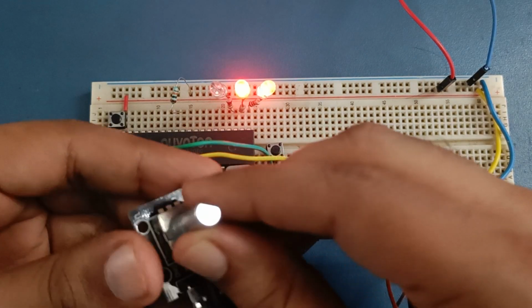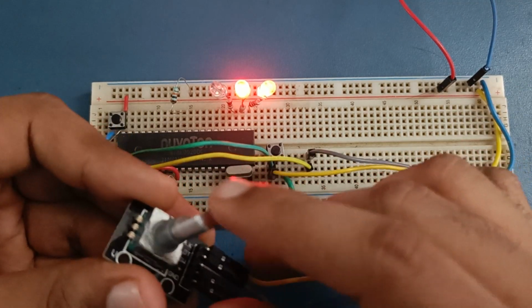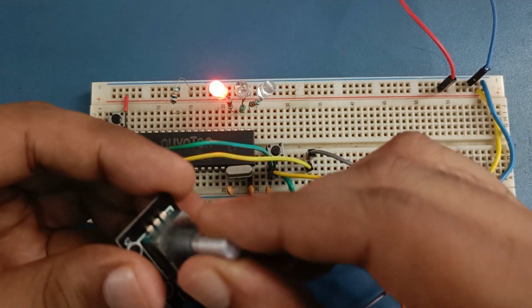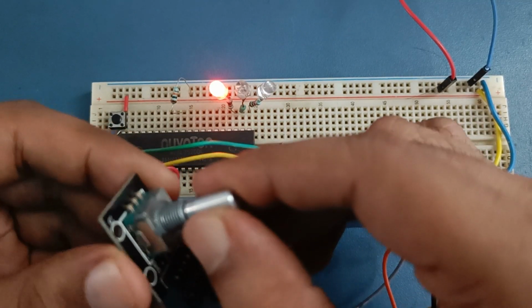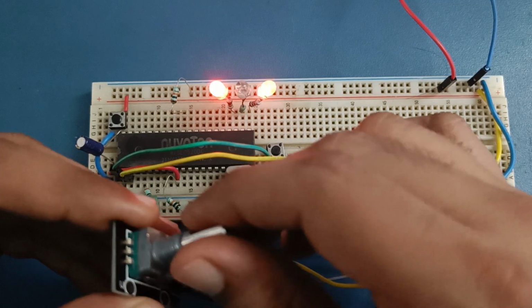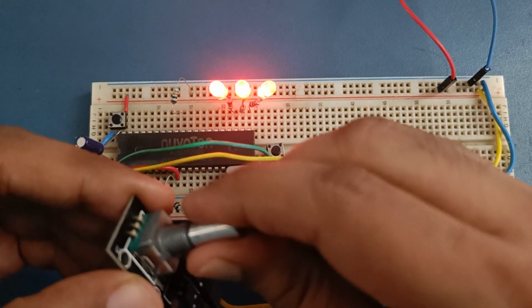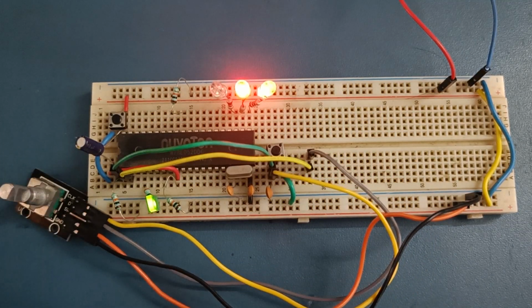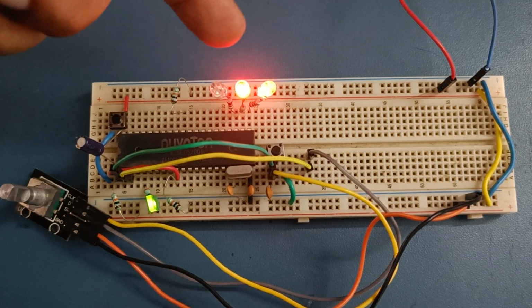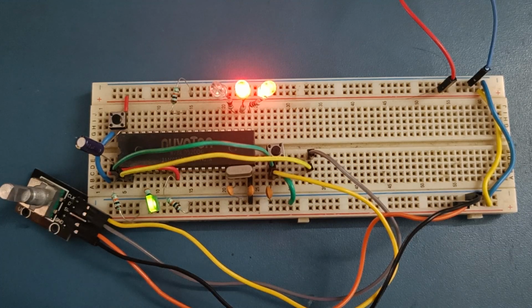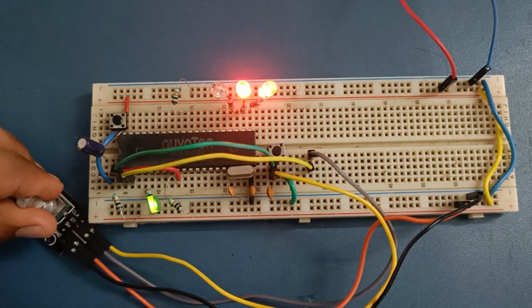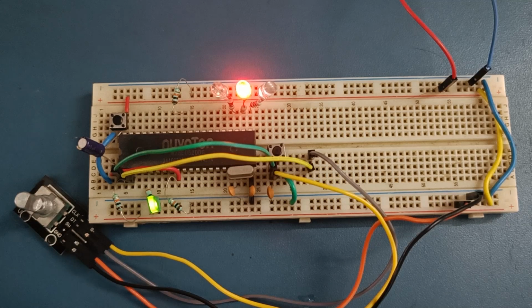Okay. In this way, we don't need any code for this rotary encoder if we are using timer 2. You can just initialize the registers and directly interface this rotary encoder to the T2EX pin and T2. So this is one of the applications of timer 2 in auto reload up down counting. And we can pass these TL2 and TH2 values directly to our application function and control an LED or anything we want with this 16-bit output.